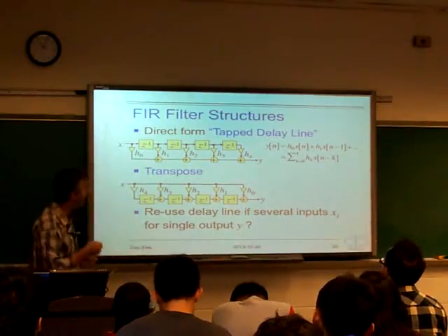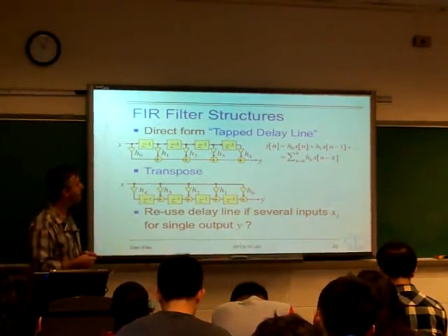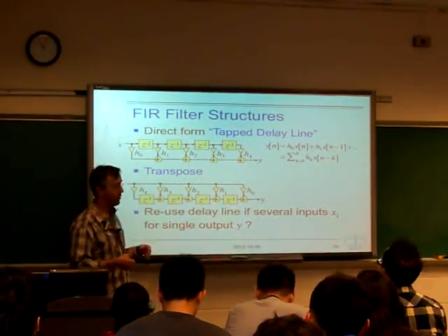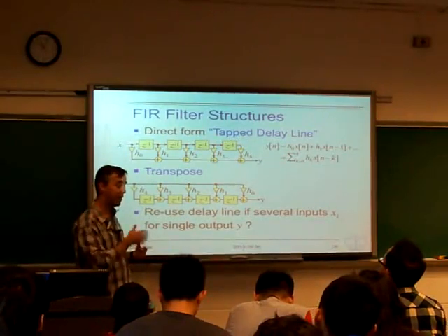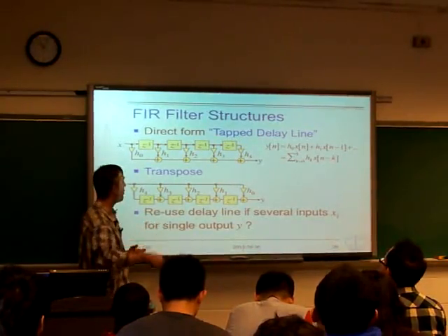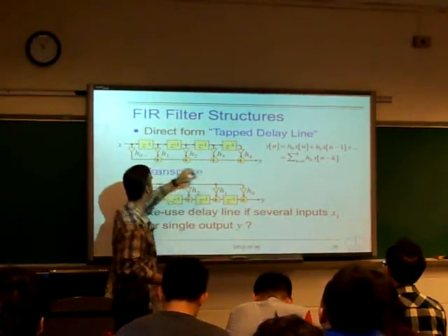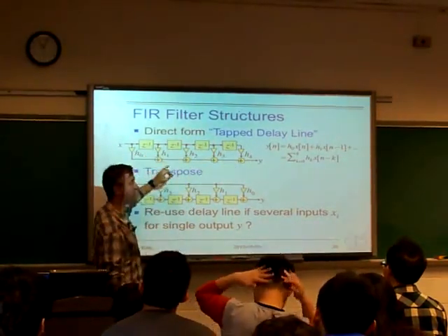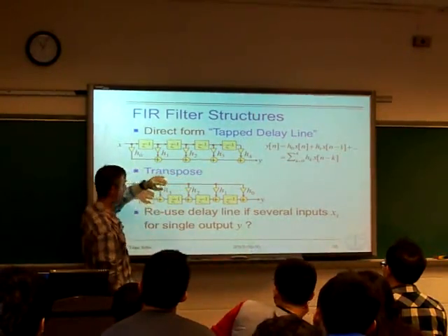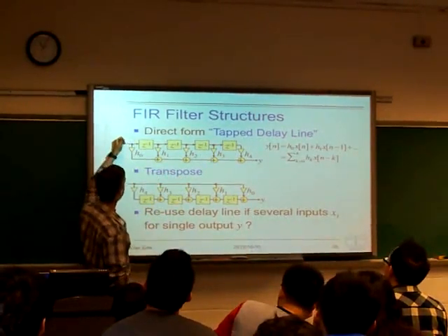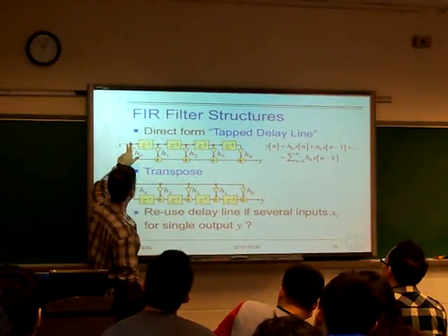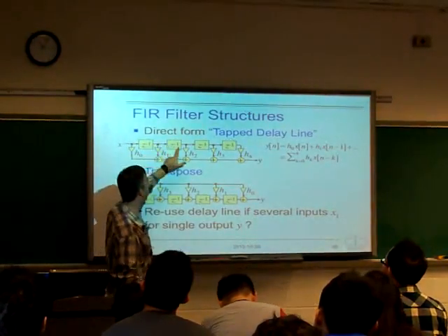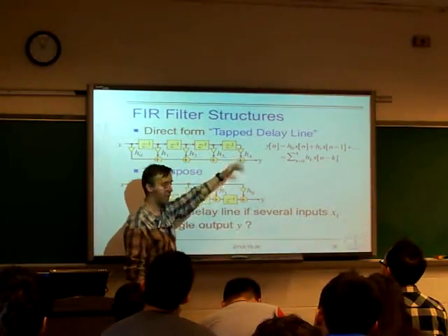So if we're now thinking specifically about FIR filters, which are these filters where we have a finite impulse response, so basically if we just have a finite number of delays, then we can write out the impulse response as gain factors on the outputs of each of these delays. So, very literally, if we put an impulse in here, then what's going to happen for each time step is that at time 0 it'll be here, at time 1 it'll be here, time 2 it'll be here, time 3, time 4, and then it'll disappear.